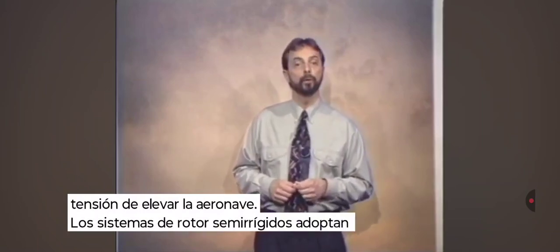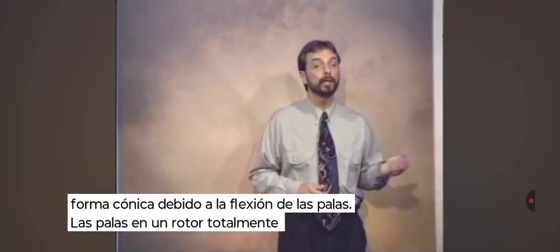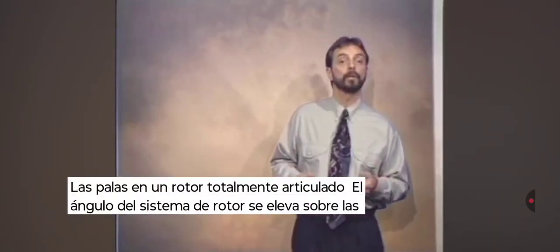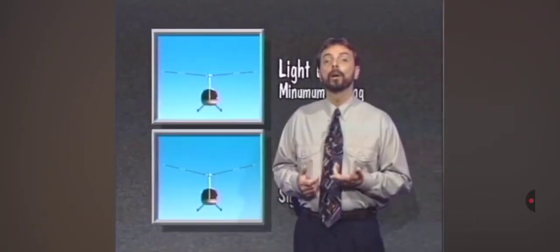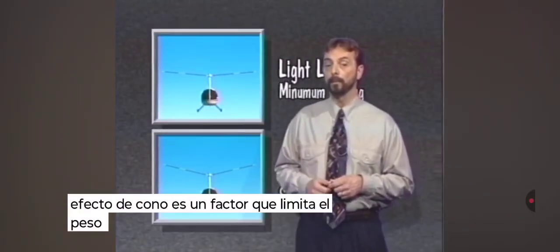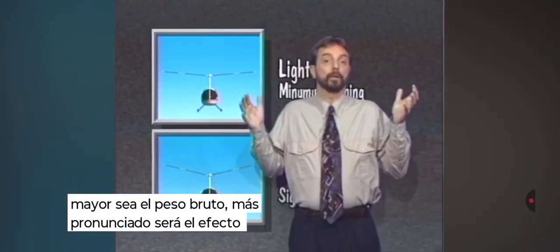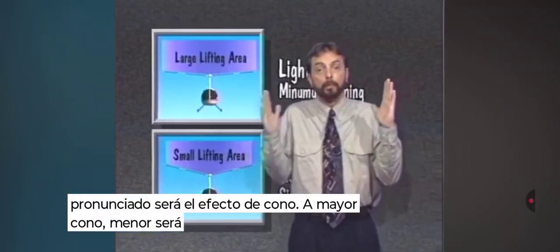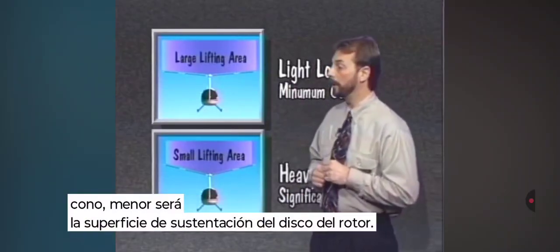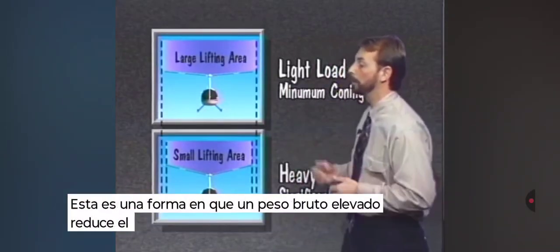Semi-rigid rotor systems assume a conical shape due to blade bending. The blades in a fully articulated rotor system angle upwards about the flapping hinges. Coning is a factor that limits maximum gross weight of the helicopter. The higher the gross weight, the more pronounced the coning effect. The more coning that occurs, the smaller the lifting area of the rotor disc. This is one way that high gross weight reduces performance.